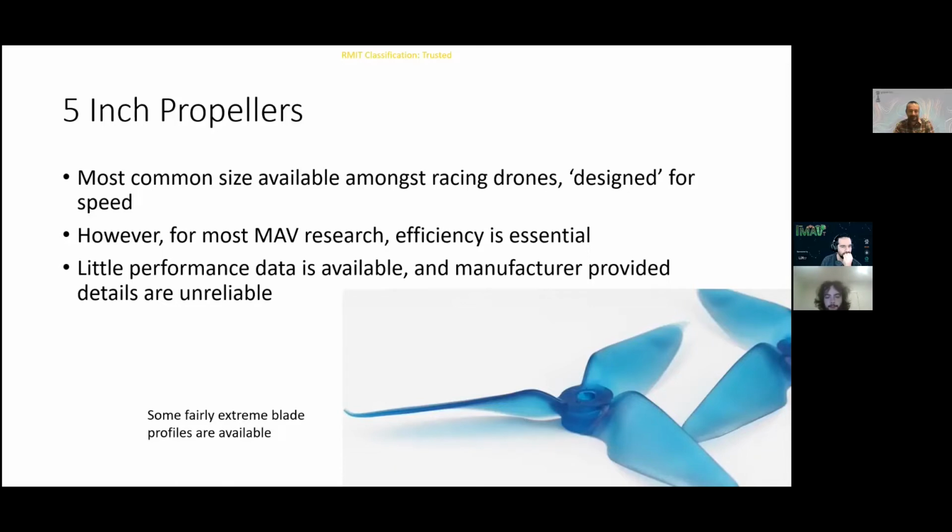is much more important. So to use that example of the Unmanned Aerial Systems wind measuring drone again, the flight plan of that aircraft is for a long continuous fast forward flight and then a fairly rapid return to the start so it can repeat that flight as many times as possible. Now, this requires, ideally, the highest efficiency that we can get in that forward flight mode to maximize data collection in a given sort of wind scenario.